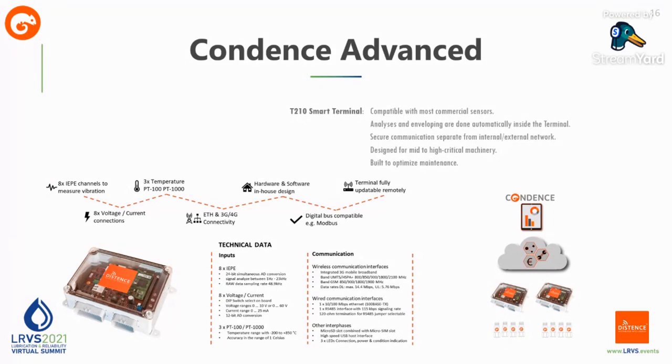So you can probably imagine that from here it's only a small step to create need-based lubrication schedules, without the need for additional sensors or technology, other than the standard accelerometers and RPM sensors that provide all the other benefits too.